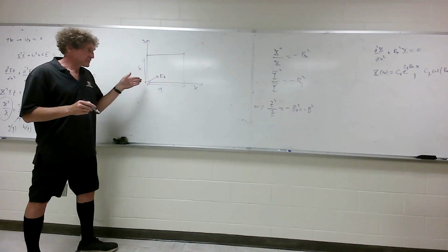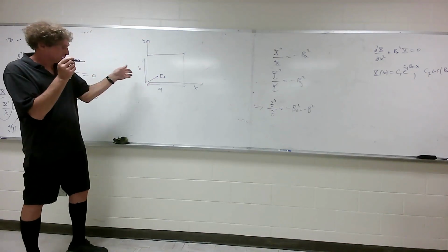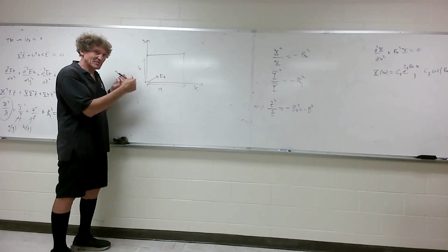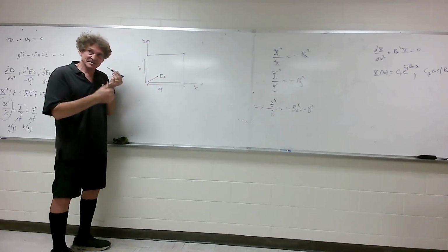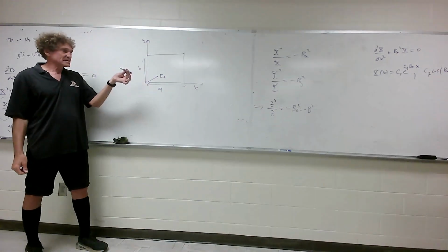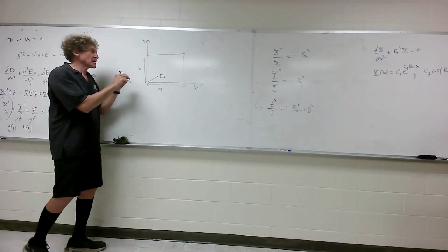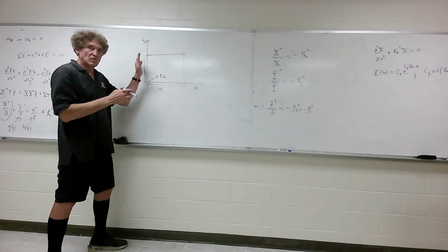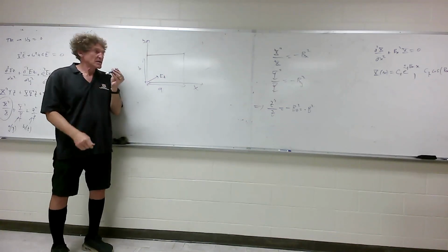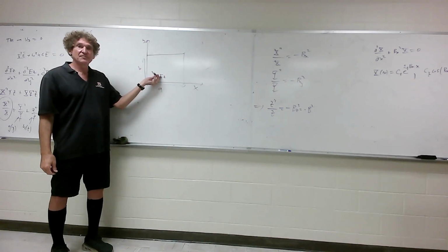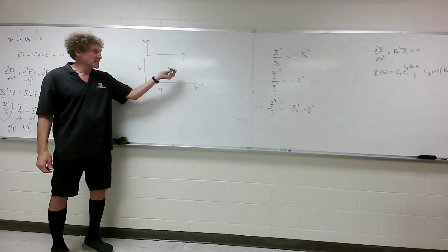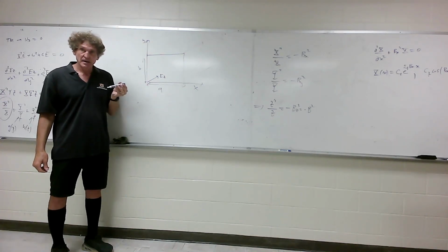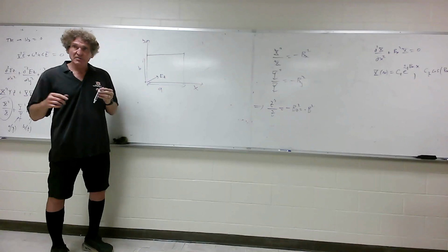And Ez, if you think about it, assume Z would be out of the board here. Look at this, if it's a right-hand coordinate system, x cross y would be z. But if E only has a z component, try to appreciate this. Remember that the waveguide comes out of the board. It's like solid walls there, a chimney you might say, coming out. Ez is the E field. It has to be 0 on that boundary, that boundary, that boundary, that boundary. Do you agree with that? Y'all follow me?